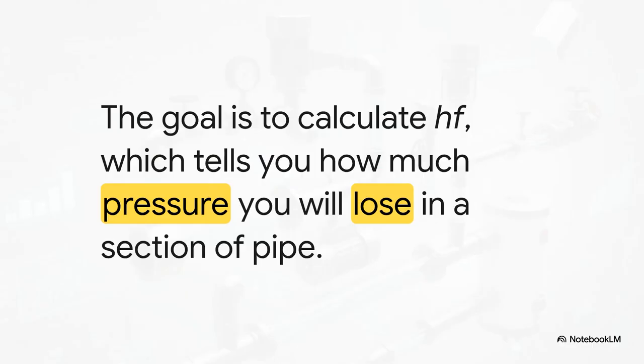So here's the crucial takeaway, the whole reason we do this. We run this calculation for every single section of pipe in our system. Why? Because it tells us exactly how much pressure we're losing along the way. That's how we can guarantee there's still enough pressure left when the water gets to that last tap at the end of the line. It's all about managing that loss.